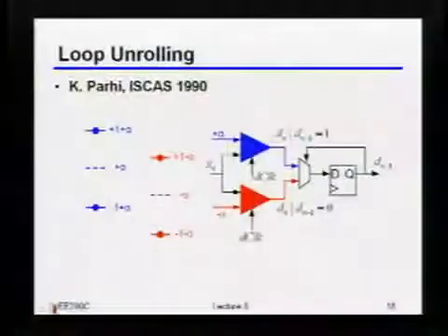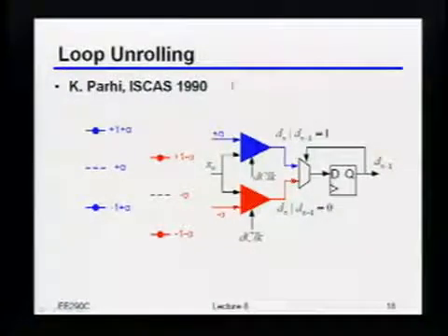But the last thing we ended on was saying that if you really want to push it, and you don't want to move all the way into CML, or even beyond certain data rates in CML, you might have to do this. There's this basic idea of not really closing the loop, but instead doing what's called a loop unrolling technique. We talked about this a bit last time, but just to make sure it's really clear, let's say we really couldn't deal with that very first tap.